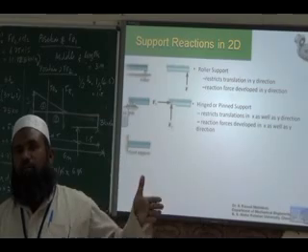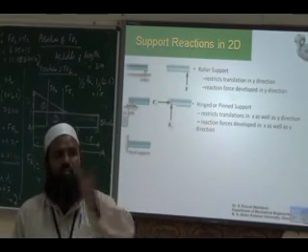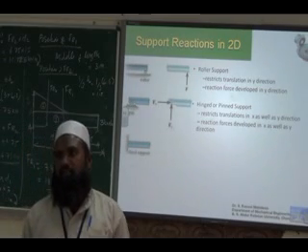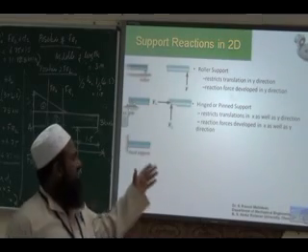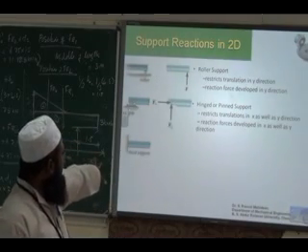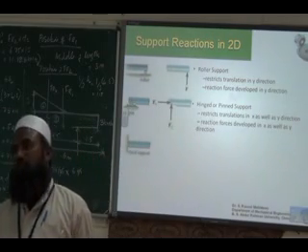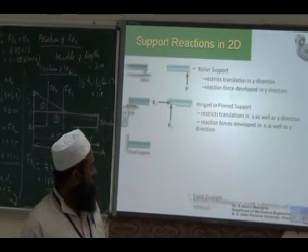Say it is a coplanar system. Okay, we consider only the X and Y, neglect the Z direction at present. So we say only X and Y. Okay, so it is a fixed support. No translation in X and Y. No rotation around Z.